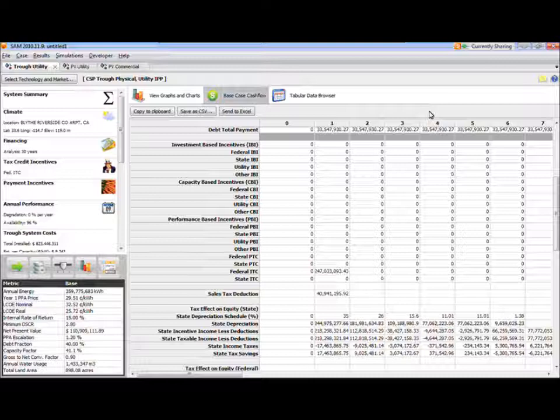So for the inverters for which those values are not available, you have to do that check yourself. So you just need to make sure that you've chosen the number of inverters that's appropriate for your array. SAM isn't going to display a warning if they're mismatched. So the lack of those values doesn't have an effect on the simulation results, just on that pre-simulation check. Okay, thank you.